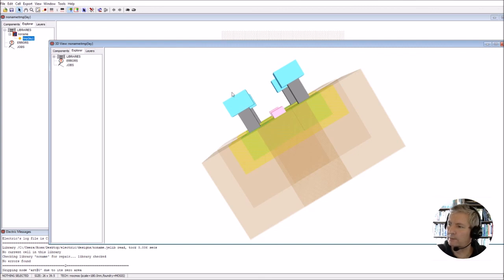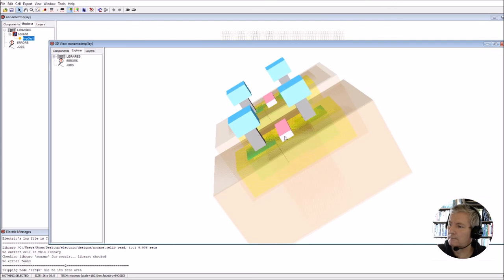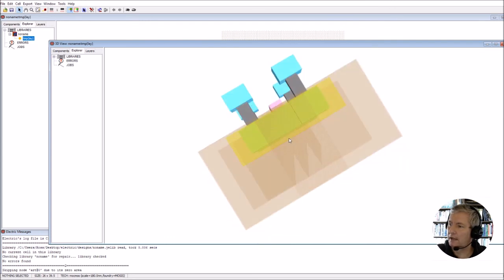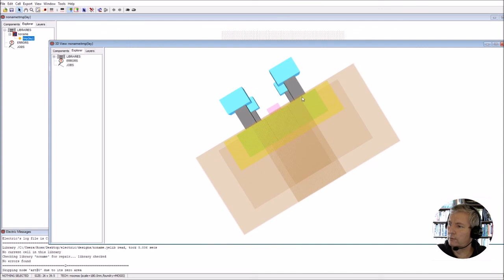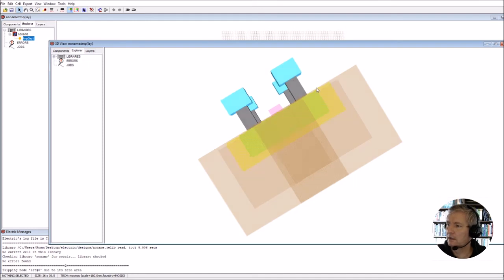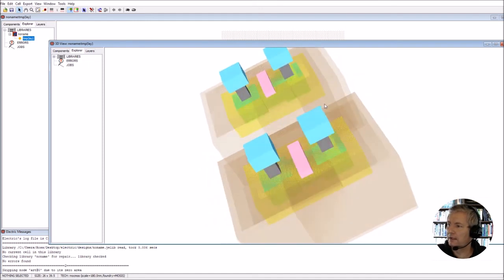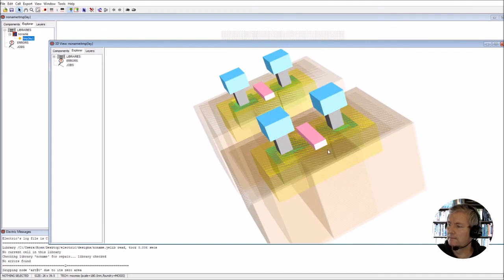So in effect this becomes, let's say we call that the source, and we're going to have the channel which runs along here underneath the gate contact, and current's going to come out through this via here up onto metal 1 again and head out there. So the current's going to come in here, down through, out through the channel, up and out through this connection, and we can see that it's sitting in a large well.